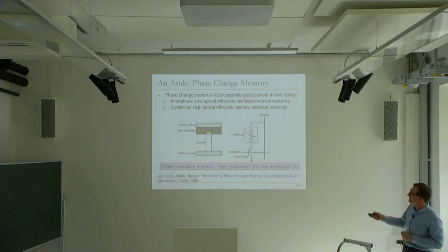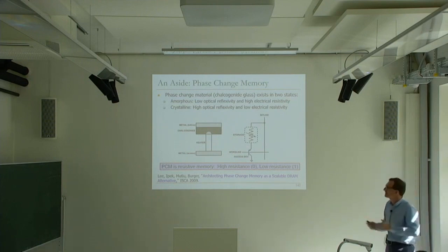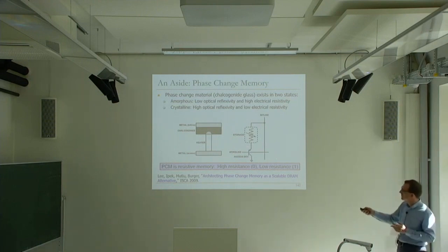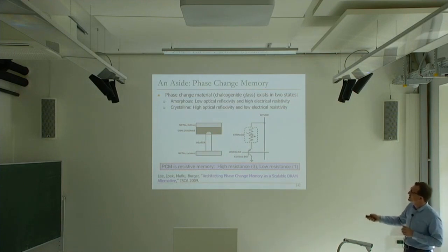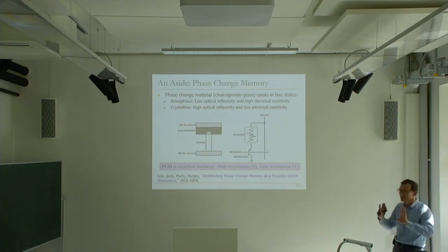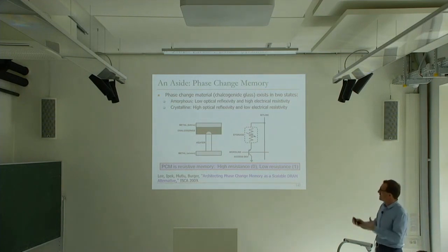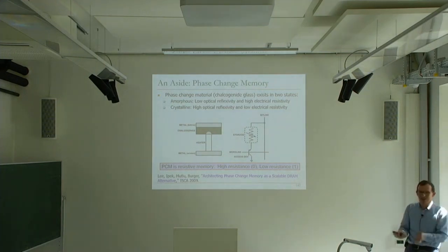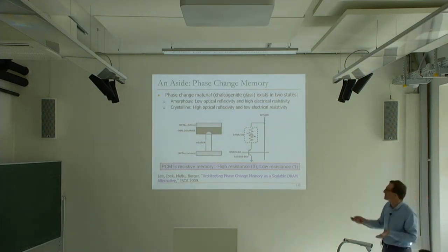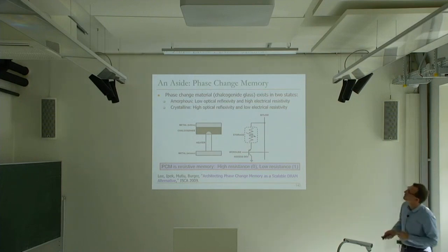And again, the word line is similar, although it's a bit turned around over here. Basically, this is the word line that enables access to the storage device. And this is the bit line. And then you have a sense amplifier somewhere over here. So essentially, the technologies are very similar in terms of the word line and the bit line structure and the sense amplifier. Sense amplifier is different, of course, in terms of how it senses, but as a block, it's essentially a sense amplifier. It's sensing what's inside the storage unit.